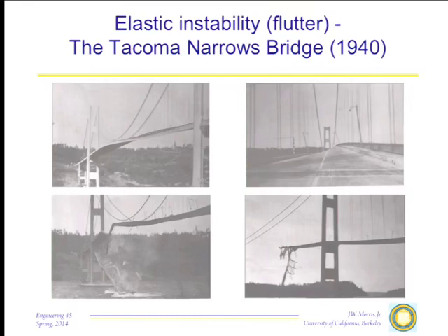But because the ones that you miss are so small, if you know they're there, it's very easy to fix them. You just put on a counterweight, change your weight distribution slightly, and you'll change that mode, and then it goes away. But it's always a serious risk.